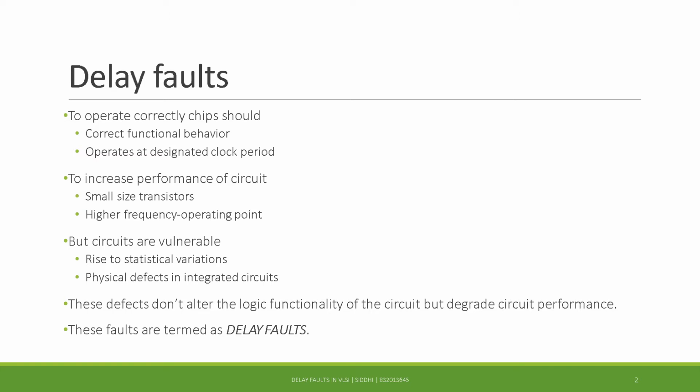physical defects in integrated circuits. These defects do not alter the logical functionality of the circuit, but they do degrade the circuit performance. These faults are termed delay faults. Hence, to ensure that the manufactured circuit operates correctly, delay fault testing is an important issue.